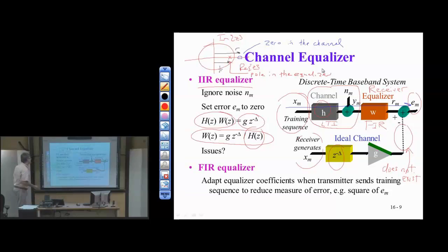Okay, what happens if the zero location were already inside the unit circle? Where would you put the pole? Right on top, right? So you get a cancellation. Cancel it out. One more case. What's the last case? On the unit circle. Yeah.